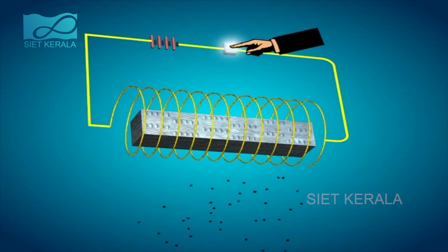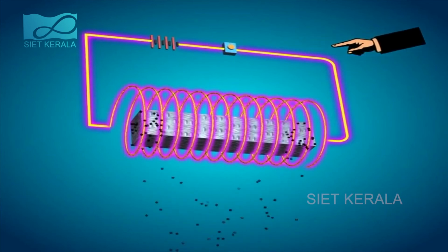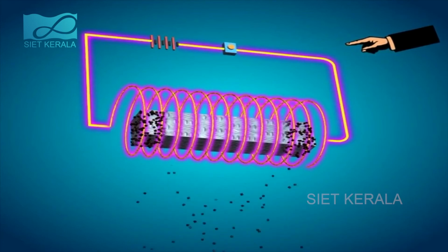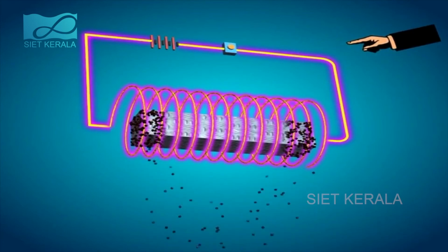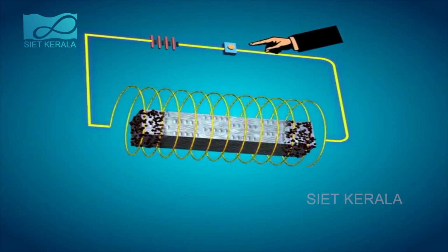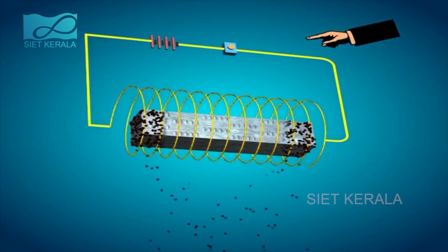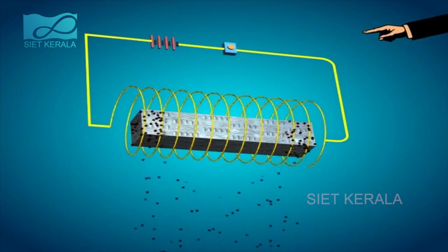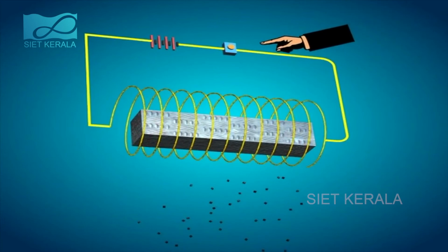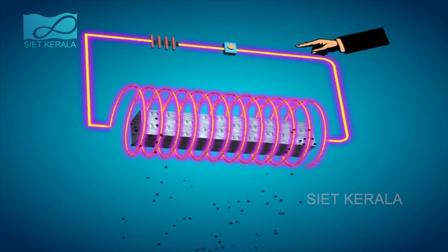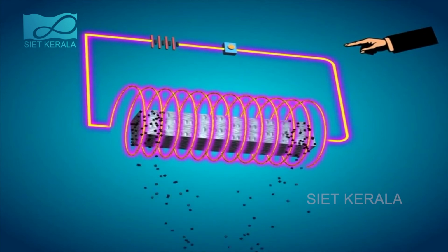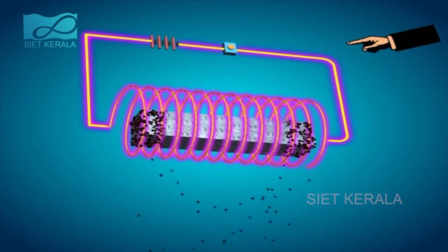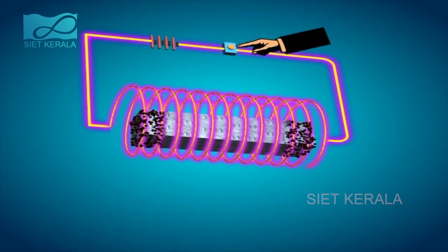Connect a solenoid through a switch to a battery. Place a soft iron core inside the solenoid. Keep one end of the core of the solenoid in contact with iron filings. Switch on the current. When the circuit is switched on, the core becomes an electromagnet. Then it attracts the iron filings towards it. When the current is switched off, the power of the electromagnet is lost. Hence, the iron filings fall down from the core.